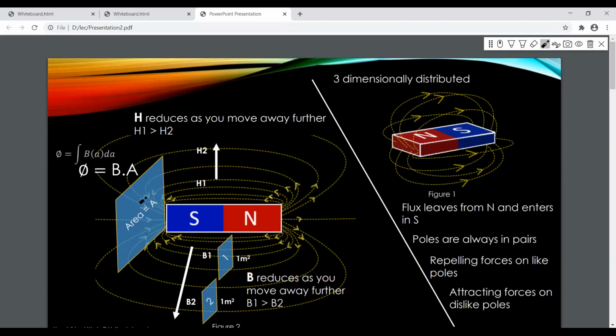But in our course, we are not going to use these continuous form equations. One reason is it's not needed unless you are going to design something. So for our understanding, we're just going to go with this simple equation, where we assume that the flux density is constant. In most cases in electrical machines, it's possible to assume that the magnetic flux density is constant because they are mostly rotating machines.